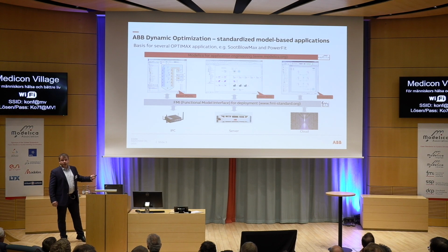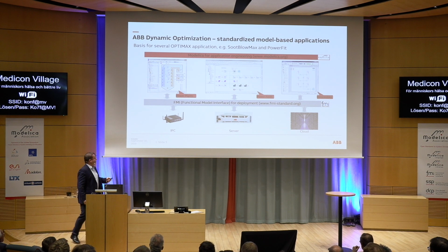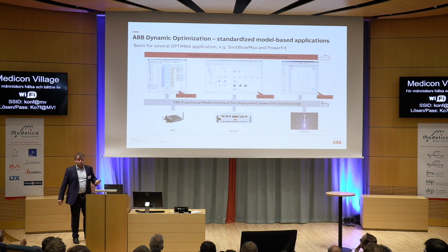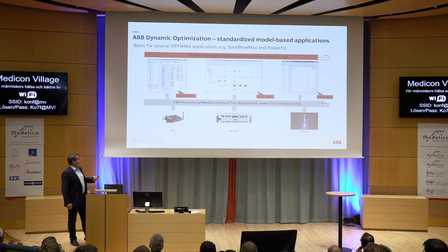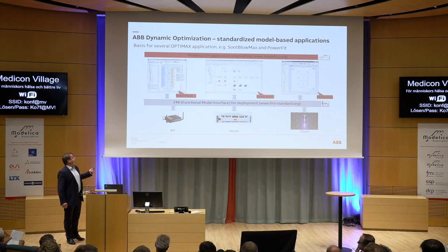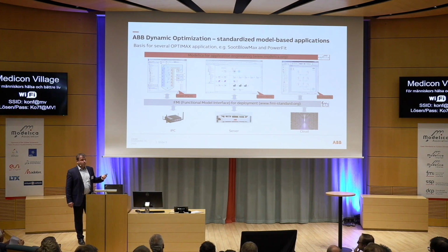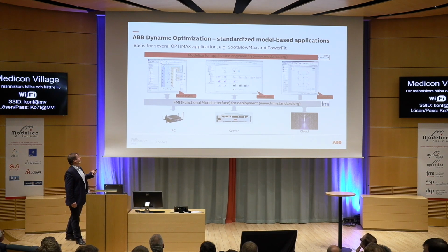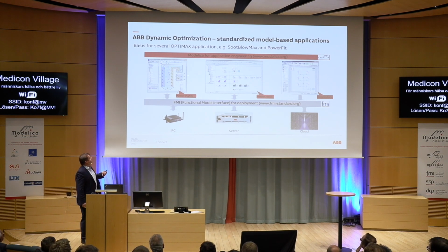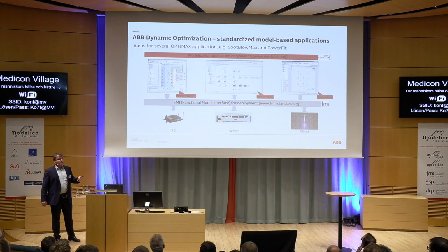No matter which physical domain we model, we translate the model to a functional model interface. I call it not mock-up interface because we use it in the real system for the control of the system. For thermofluid, Dymola has always been the best tool, and it is still the best tool due to its really blazing fast user interface. For other systems, we use the Modelica tool by ISI simulation, and we increasingly are using OpenModelica. No matter which tool we use, we can load the same Modelica libraries and generate the same FMU.